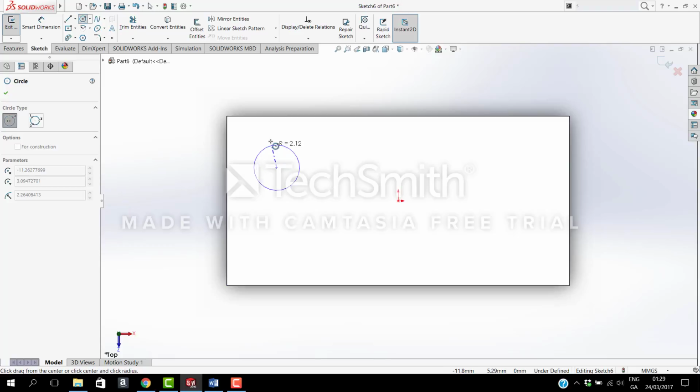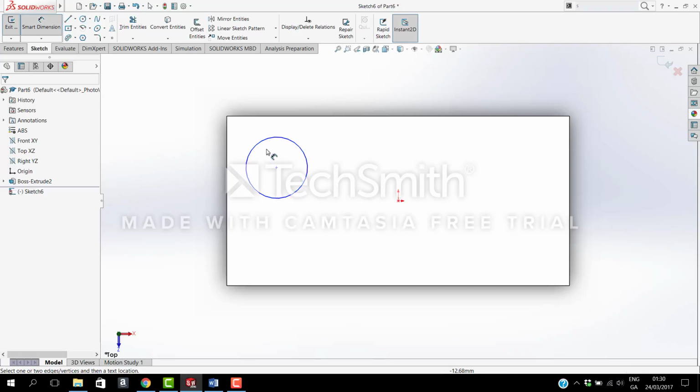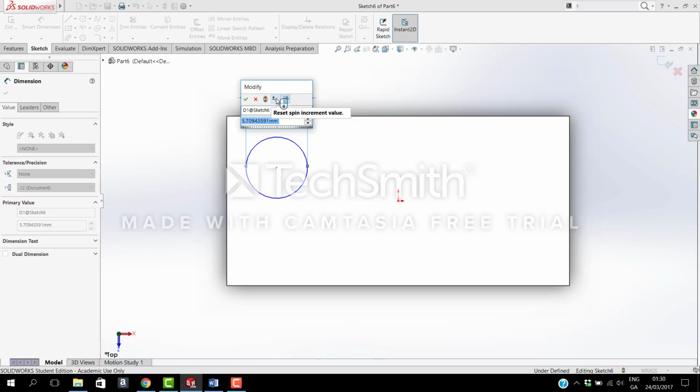So I can draw my first circle at an approximate size on the face. Once again, by holding down my right mouse button and dragging my mouse upwards, it'll initiate the dimension command. And I can dimension the circle to diameter 4.8.